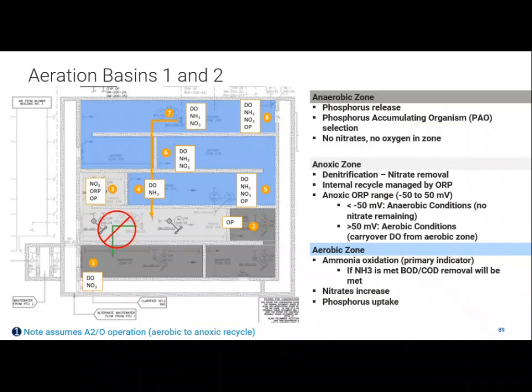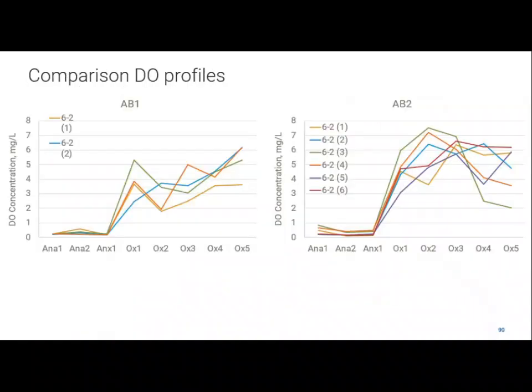Yeah, and how it's going to. What do we want to see here? So we've gone through anoxic and aerobic conditions. What's going to happen to that phosphorus condition by the time you're into that aerobic condition? What do you want to see happen? Yeah, you want them to be taking that poly P up and growing as fast as they can. You want them to be consuming their PHA and storing their phosphorus. And then just going through the back end of the plant and getting to the very end, and this is essentially your effluent, right? All right, so this can give us a sense of what happens as we go along the length of our aeration basins. All right, so let's look at some profiles. So here's the DO.